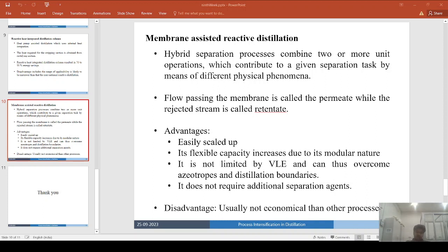Now, adding a catalyst to convert the system into a reactive high G distillation is very possible. The solid catalyst in the wire mesh packing allows for the potential of high G for solid catalyzed gas liquid reactions and even for reactive distillation. As early as 1999, Dow Chemical successfully introduced one of the first chemical applications of reactive packed beds, namely the reactive stripping of hypochlorous acid.